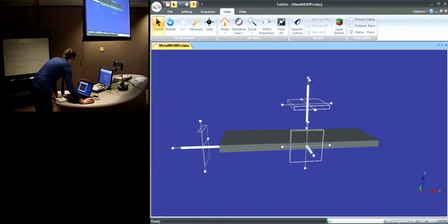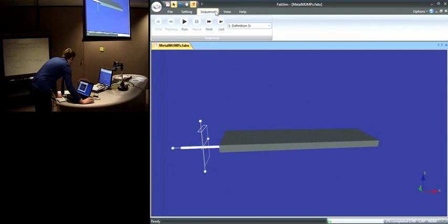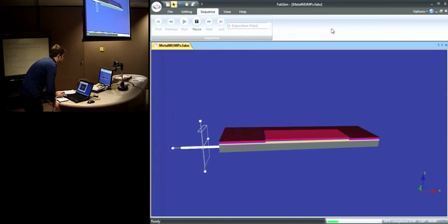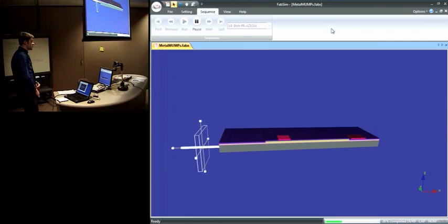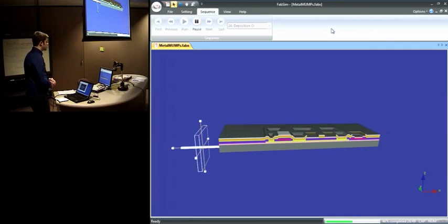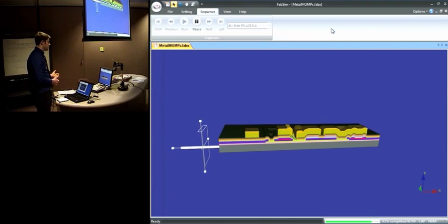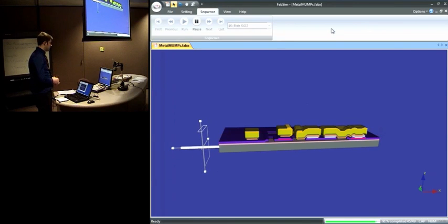So here we have 49 steps. You'll notice in FabSim that the deposition and lithography processes are pretty straightforward and quick. Where you run into a little bit of simulation time is with some of the etch steps, which will take a little bit longer than others. That's because it's using a similar algorithm as our standalone tools like Intella Etch or Recipe.